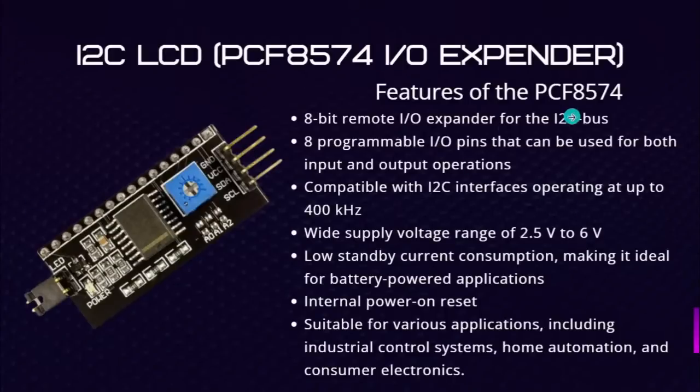Here I provide the features of PCF8574. It is an 8-bit remote input-output expander for the I2C bus, with 8 programmable input-output pins that can be used for both input and output operations.